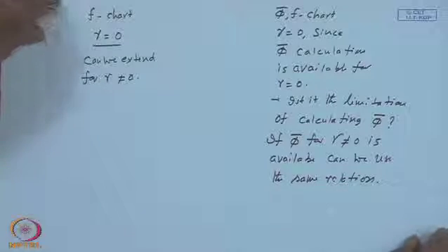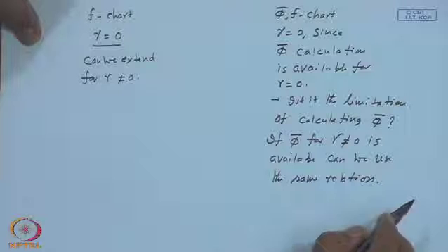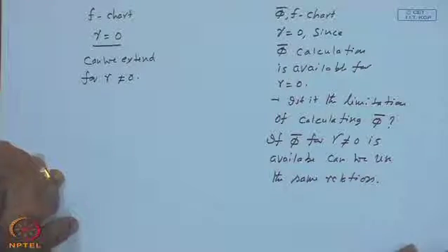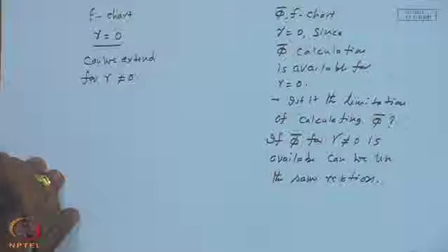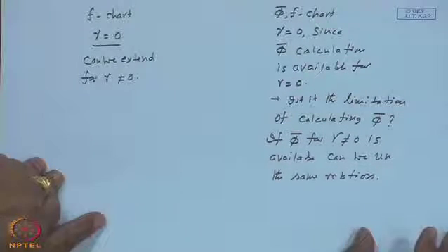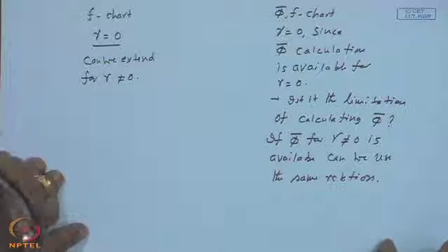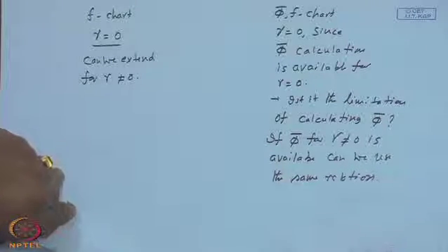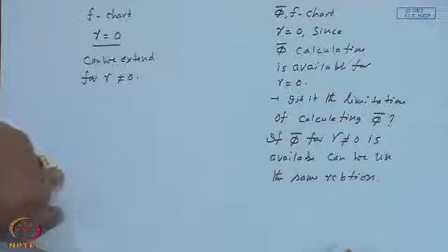Somebody may take up this problem, though if I remember right, Collares-Pereira and Rabl suggested that for concentrating collector or gamma not equal to 0 value, replace this phi bar and use the same correlation. However, some verification needs to be done based upon the simulation results.